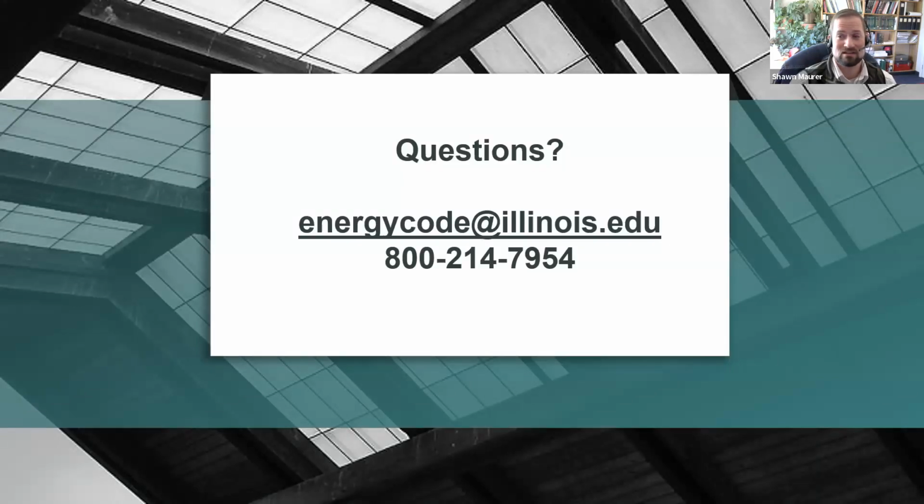If it is conditioned and it's a sunroom addition to the porch, you've got a large amount of glazing, there are some special requirements for sunrooms, as long as they remain thermally isolated from the rest of the house. But the sunroom itself is conditioned. There are slightly less stringent insulation requirements. If it is communicating freely with the house, it's not thermally isolated, then it would have to meet those envelope requirements, the R20 and the R5.